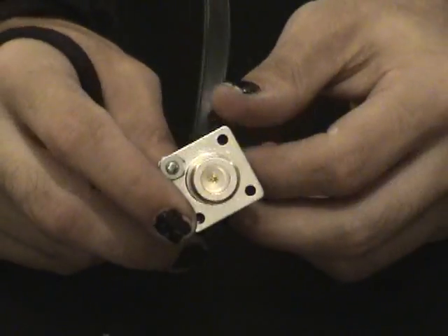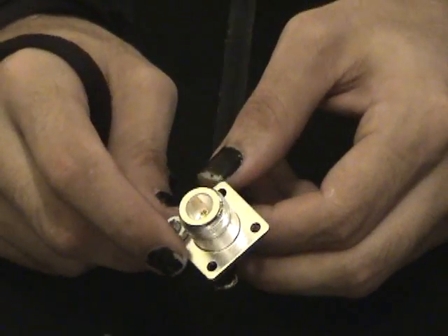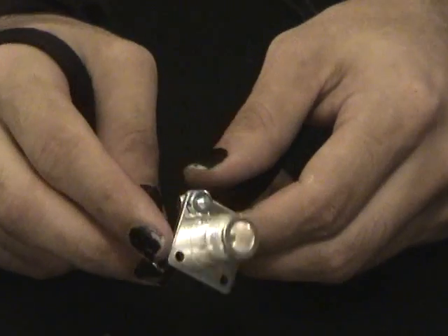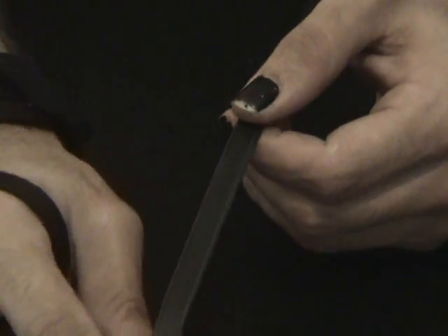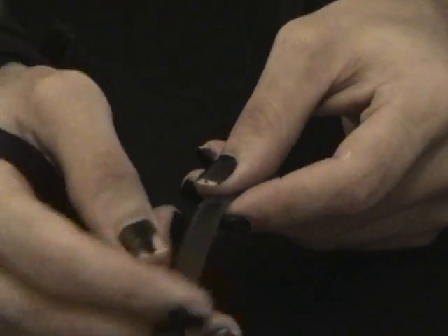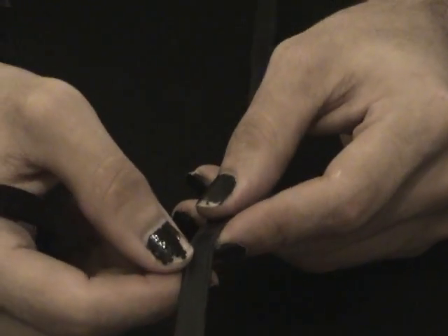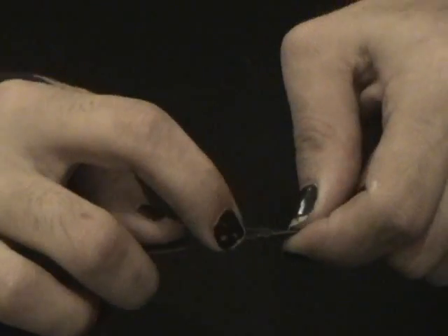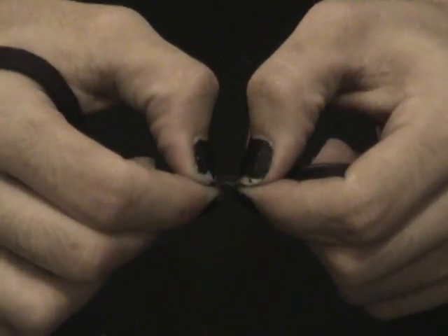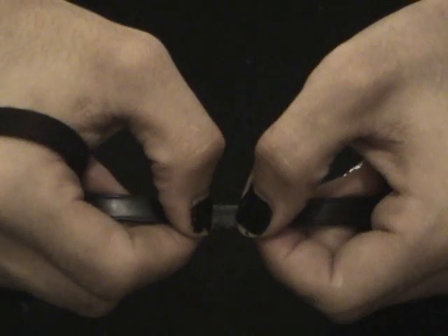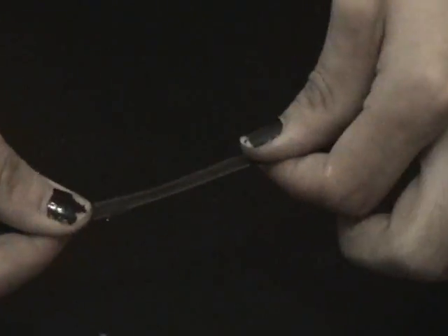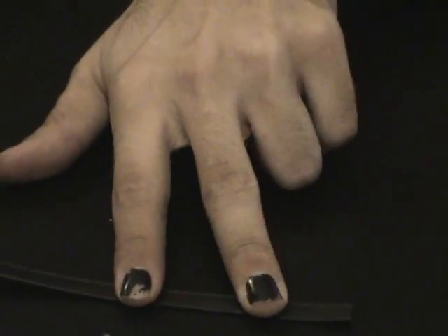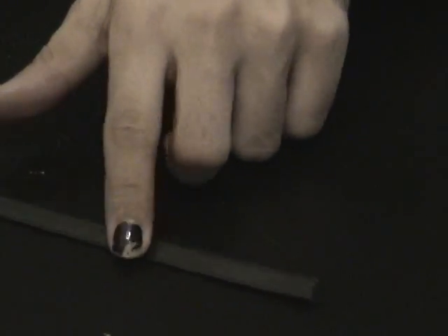Now, you're not supposed to be using a connector like this. You're supposed to directly solder your coax in, but I didn't have anything that'll actually fit on my SWR meter at the moment. Then, X amount of inches up, in this case it was 5 inches up, you need to actually break the copper away from the twin lead right here. So there's actually a 1/4 inch notch that's just been completely ripped away. And then about 12 inches of ladder line or twin lead, depending on what your region calls it.